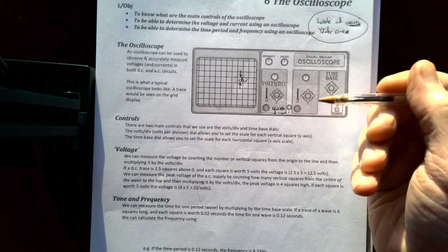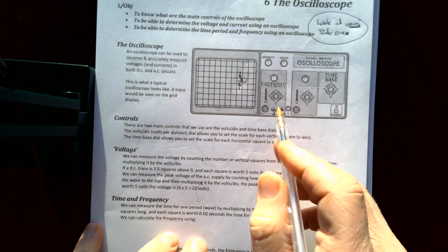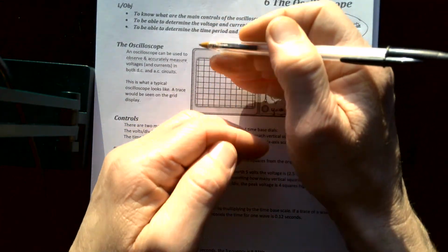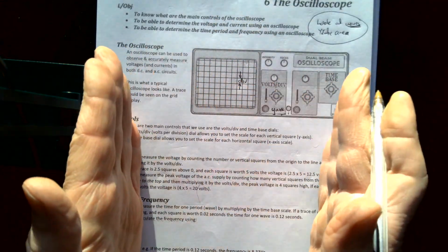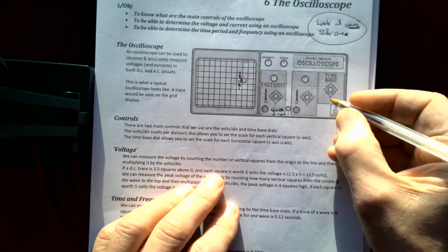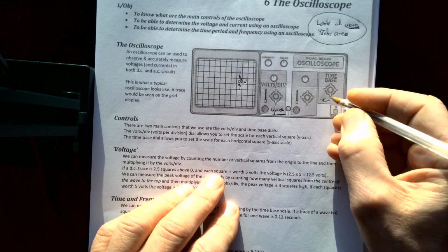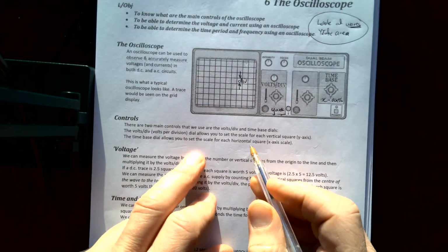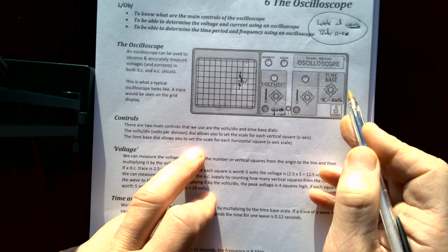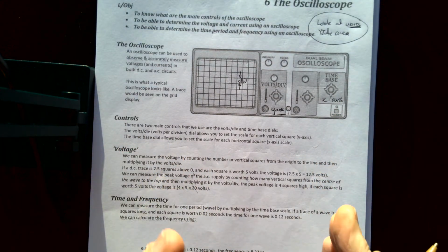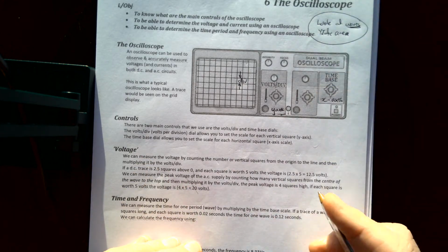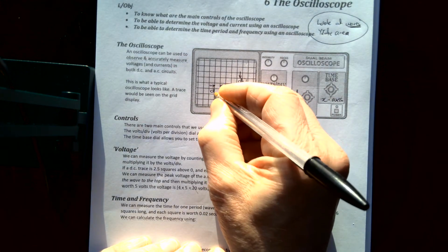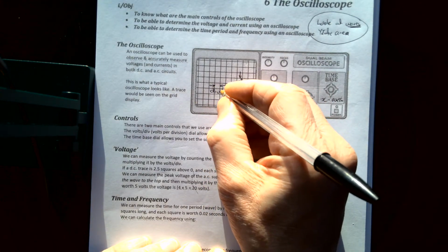Just a reminder of the lesson coming up, so I'll keep this nice and short. Similarly, the rate at which it goes across: you can make your waves taller and shorter using one control, and wider and narrower using this one. So this is your x-axis, or should we say time axis, because they are both on the same principle. So many milliseconds per division, usually, maybe microseconds, depending on the scale that you click it round to. But again, you've got your division in time.